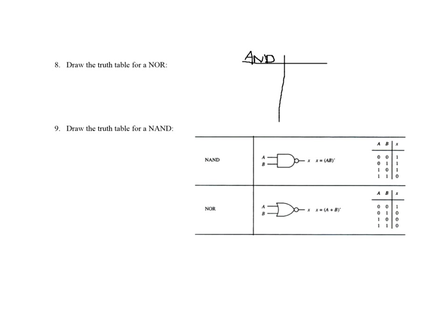An AND gate. Well, the possibilities are 0, 0, 0, 1, 1, 0, and 1, 1. And in an AND gate, you know the only time you're going to get an output is when you have both of those on the input. So these are all zeros. That's a straight up AND. But a NAND is the opposite. The NAND is exactly the same thing, but opposite, because you have a NOT on the end. So this would be 1, 1, 1, 0. So that was a way that I could remember which ones were which. If I had trouble remembering, I would just resort to something like that and jot it down.